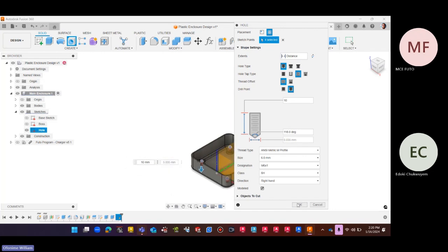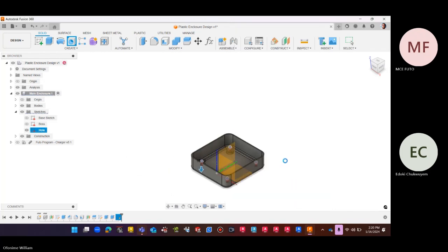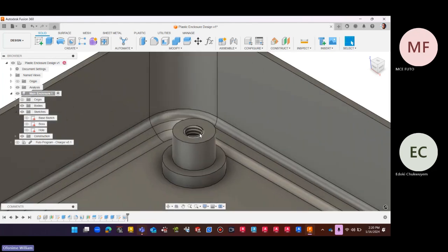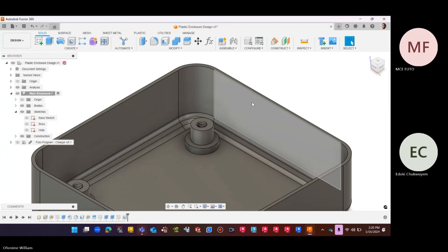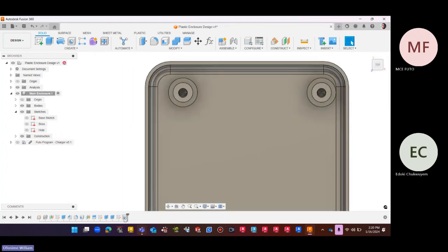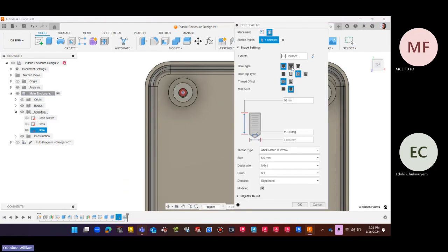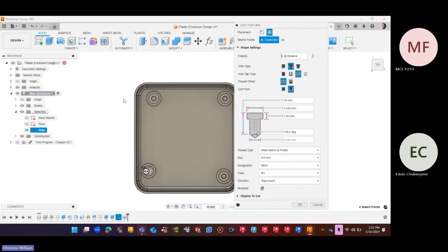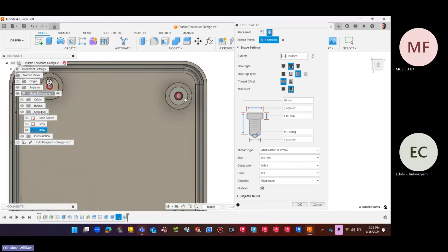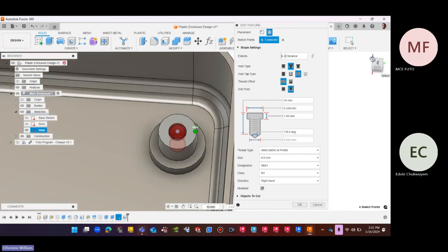So click on OK, just to accept. One more thing, notice this jagged edge on this top. So we'll go back to that hole, do an edit, and switch to a counterbore to have a more uniform surface, then we could sink our screw in as well.